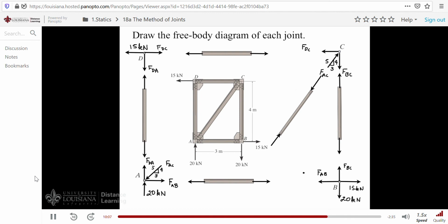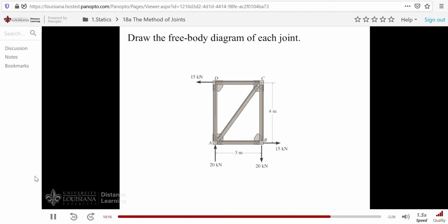And as I stated earlier, we apply the equations of force equilibrium to each joint, and then we can figure out all the forces. Now, before we end the lesson, let's re-review the same problem we just finished, except now we won't draw the members, and see if we can just draw the joints, understanding what tension and compression really is. We'll begin in joint D. How many forces act there? Well, we'd have to put 3 on our free body diagram, wouldn't we?